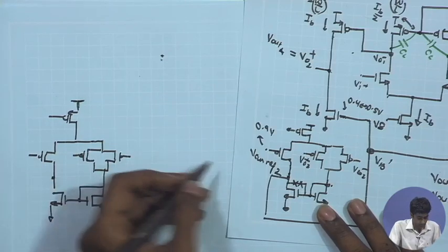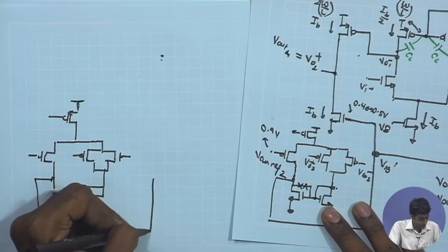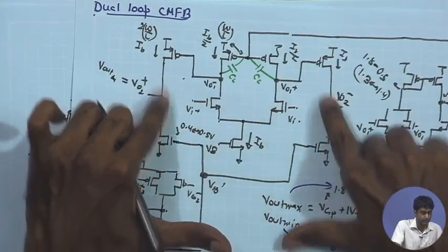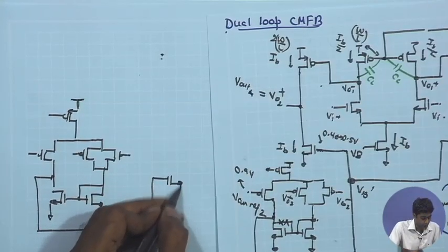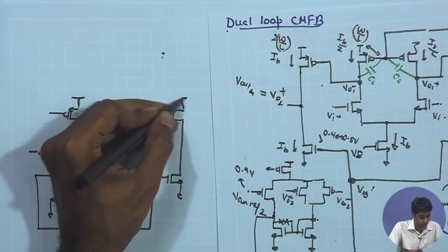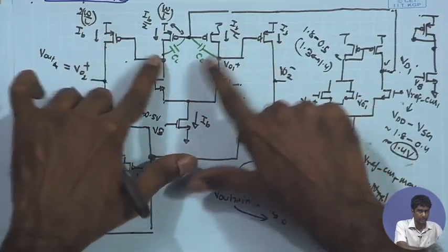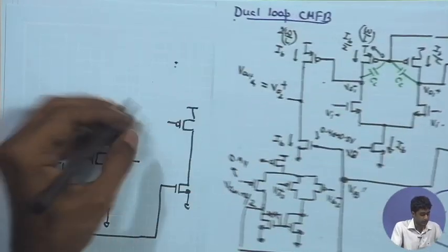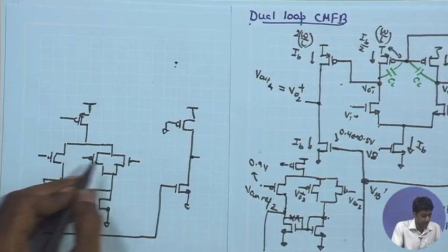This is going to the NMOS stage, and for the common mode operation, once again we can tie these two nodes together. Therefore, these PMOS and NMOS become overlapped, and we have an overall common source amplifier with NMOS as an input device and PMOS as load device. The gate voltage of these two PMOS is going to be AC ground, because they are coming from the previous stage, the first stage, and that is a fixed DC bias. So the gate voltages of these become AC ground, and our output is taken at this point, which is coming back to the input.